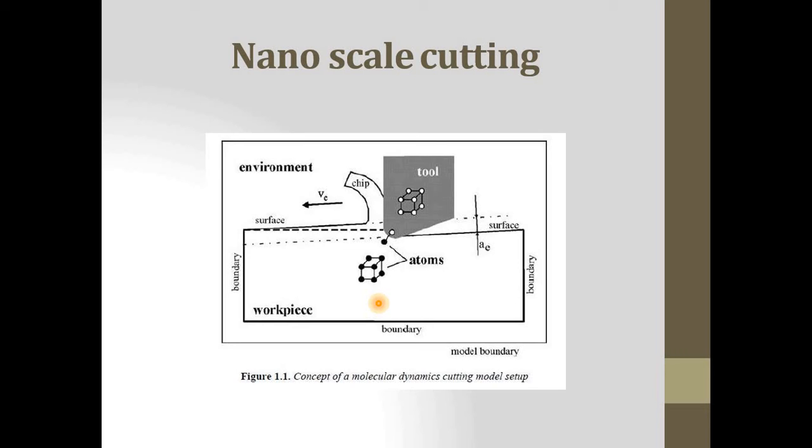However, these advantages are combined with many disadvantages and great loss of information in carrying out the atomistic simulations. With pure 2D models, it is impossible to sufficiently describe the 3D crystalline structure of a metal, and hence no realistic slip system or dislocation motion seems possible, and no realistic behavior can be expected.